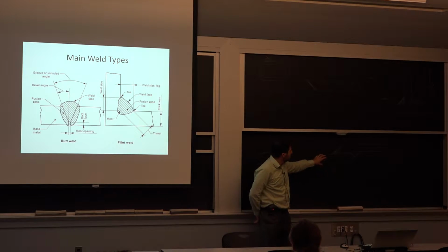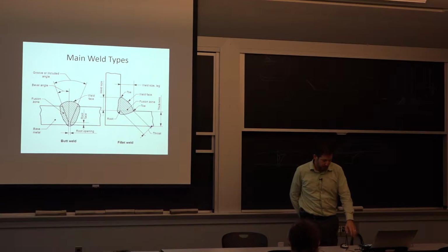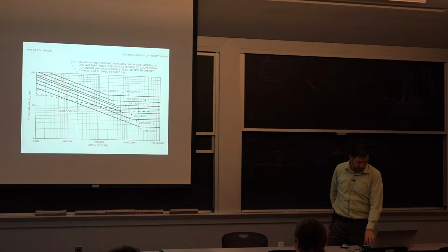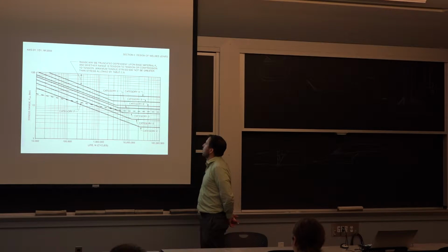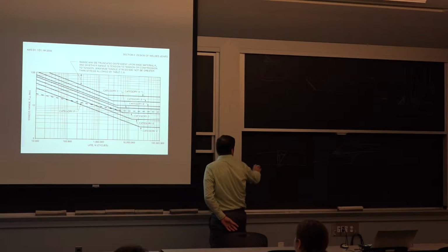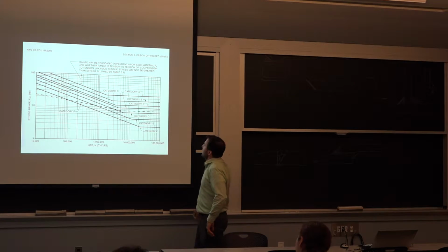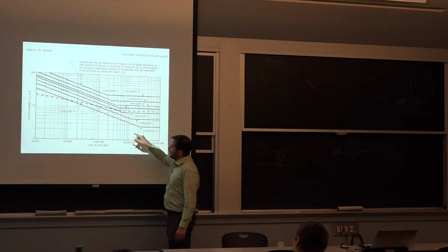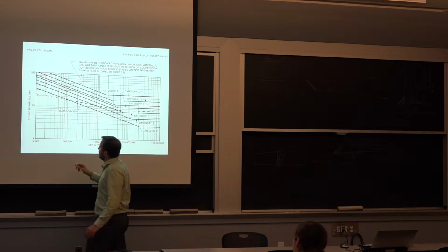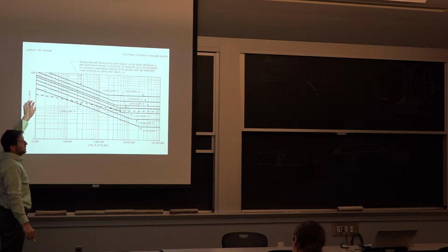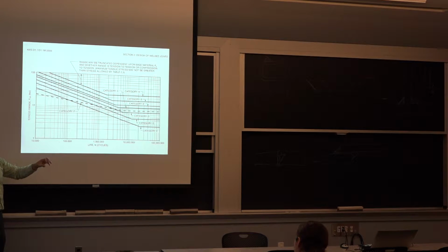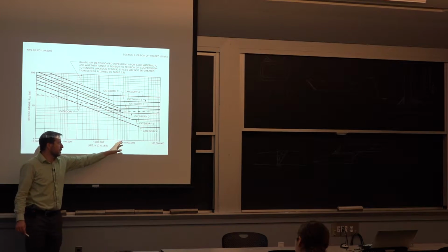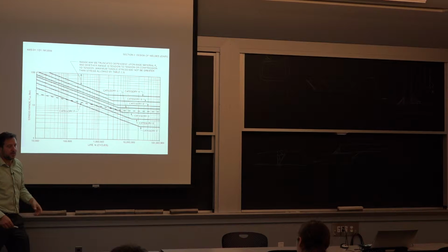So between those two extreme scenarios, you have a full range. So I do want you to see this chart just because it speaks to how your capacity will change depending on how the weld is being done. So the category, so this is fatigue. What we're looking at here is the allowable stress. It's not the failure stress. It's what you can put on the structure and meet the code. And this is the number of cycles that you expect to happen during service.